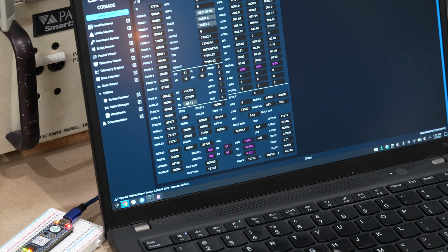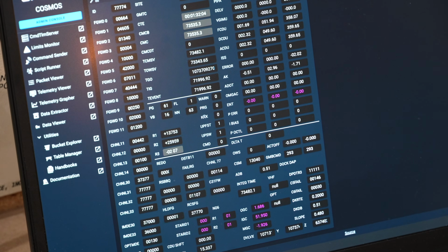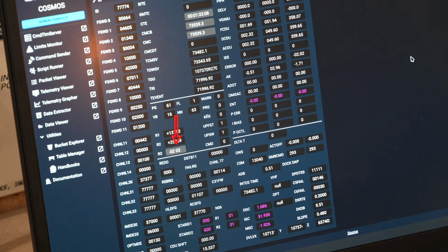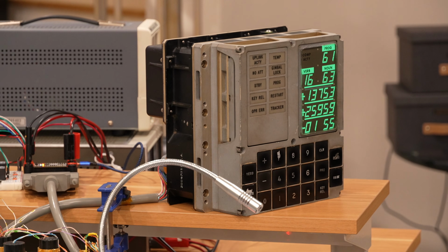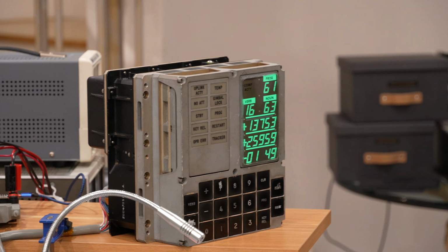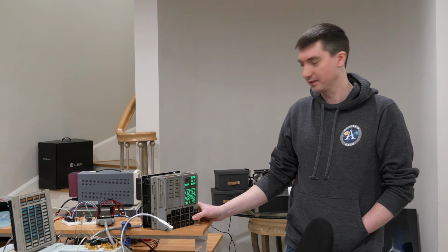That would be easy to show here. Where is the countdown? Should be in register 3. Yeah, it's doing it. It's jumping 2 seconds at a time because the DSKY is also jumping 2 seconds. Oh, okay. High fidelity transmission. The AGC telemetry for the most part is half a hertz. There are a few things that come down at 1 hertz, but it's mostly half a hertz.